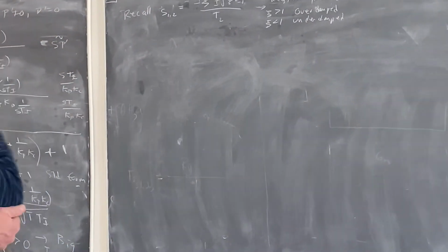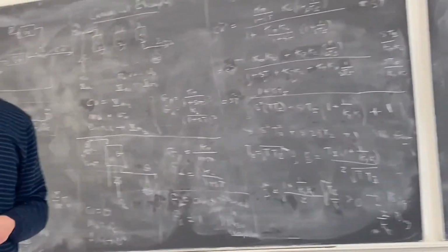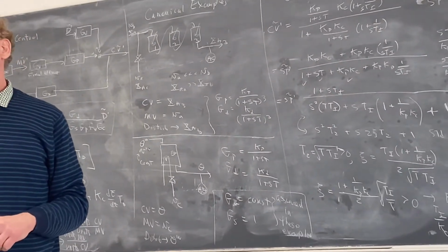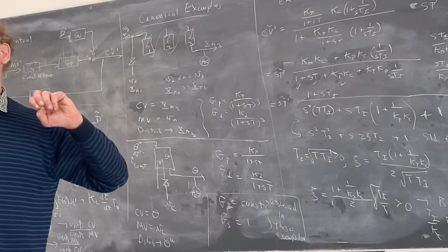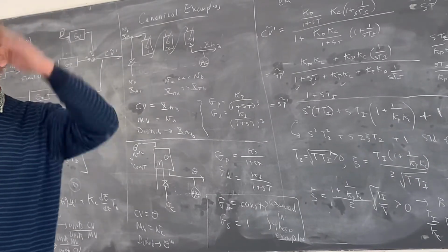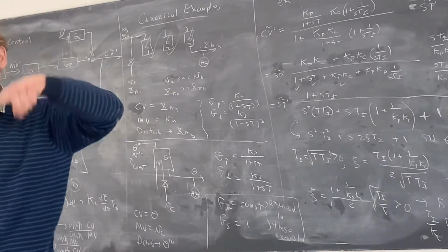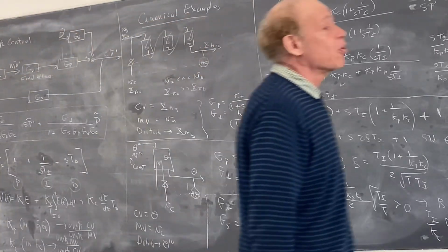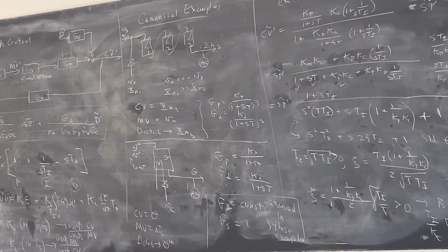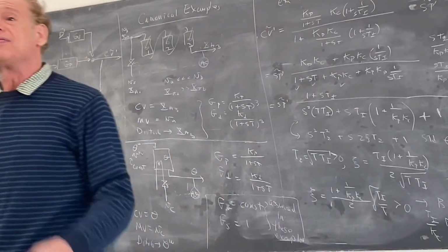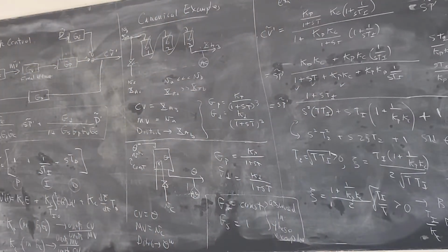And you could imagine that I could get to situations where, maybe in this example, I'm not going to get unstable, but it's certainly much more oscillatory. It's going to oscillate faster and faster. If I have a more complicated example, it could actually become unstable. So why don't we invert this? This is a very unusual example, and this is why I picked just PI control, because I can actually invert this.